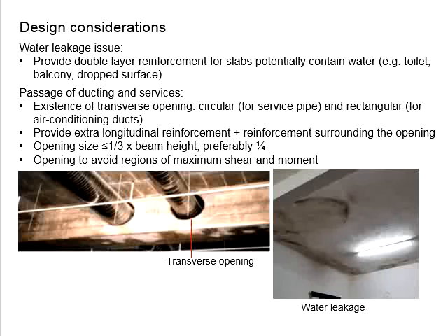Now you need to have the ducting and services passing through the beams. You cannot allow the services to pass under the beam as you don't have sufficient space, and if you pass under the beam, it will be seen by the general public. That means the most feasible way is passing through the beam.